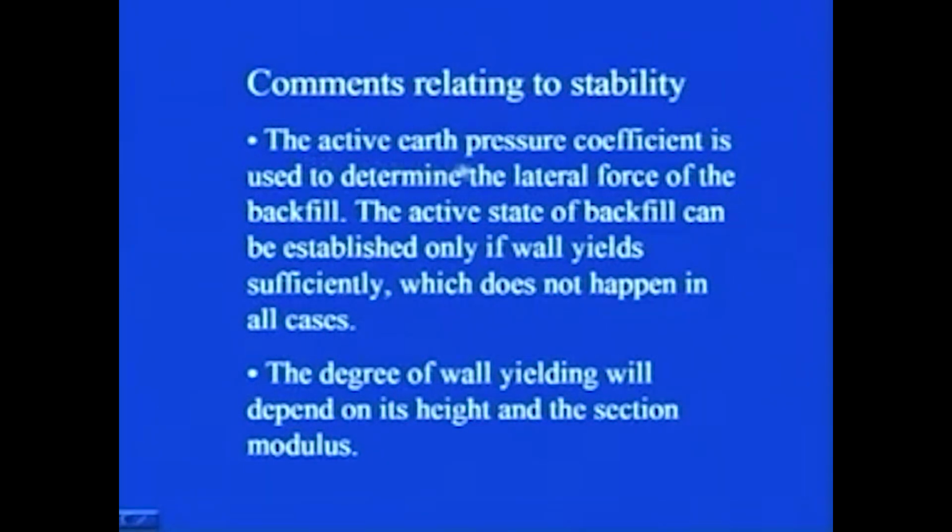Then, the active earth pressure coefficient is used to determine the lateral force of the backfill. The active state of backfill can be established only if the wall yields sufficiently, which does not happen in all cases. This aspect we have already discussed: for any soil to enter into either the active state or the passive state, the wall must move or yield sufficiently so that those conditions are generated.